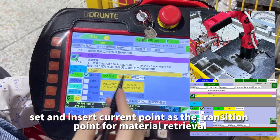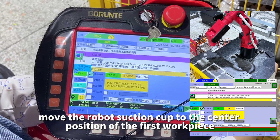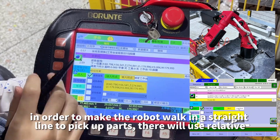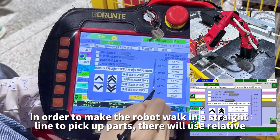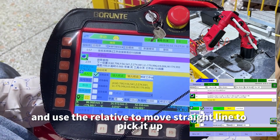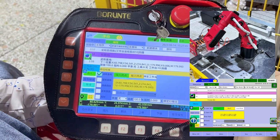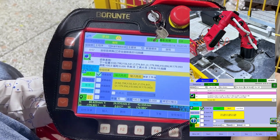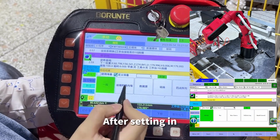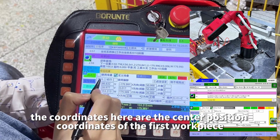For material retrieval, move the robot suction cup to the center position of the first workpiece. In order to make the robot walk in a straight line to pick up parts, we will use relative. So we set the first point of the stack above the workpiece, and use the relative to move in a straight line to pick it up. After setting it, the coordinates here are the center position coordinates of the first workpiece.